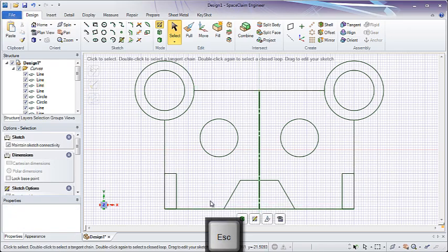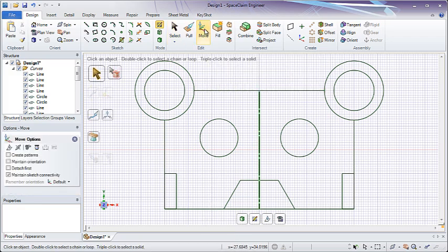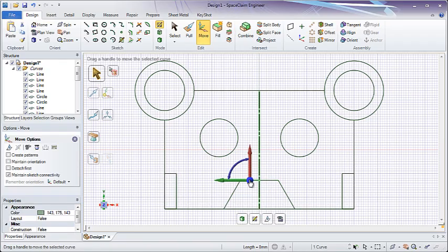What I'd like to do is have more control, and to do that, I'll use the Move tool. We'll look at Move a little bit later, but I thought it was important to show you how Move can be used in a sketch. I'm going to select on one line here, and our second line here by holding the Control key. Notice I have two curves in my selection.